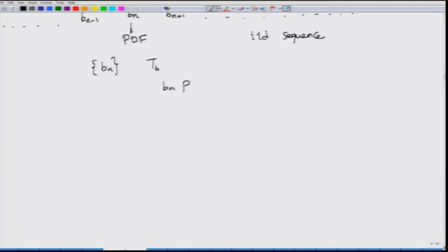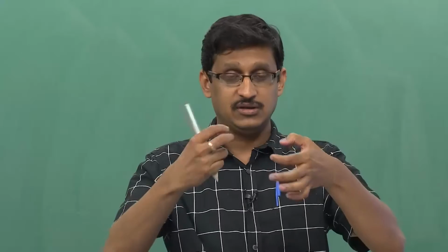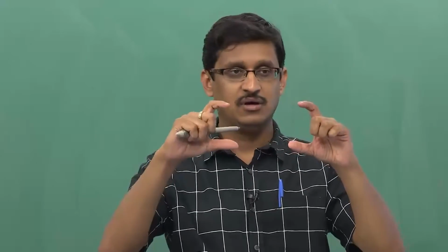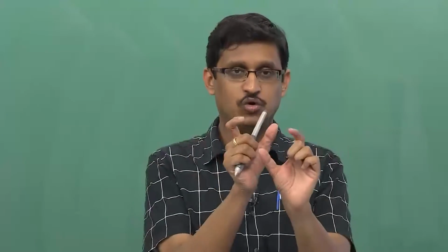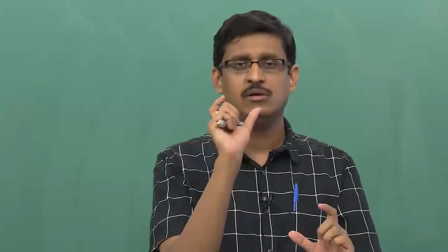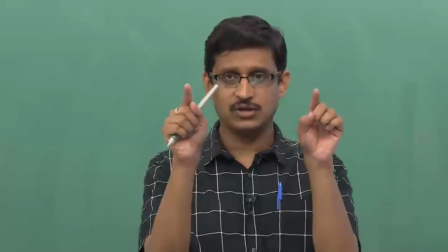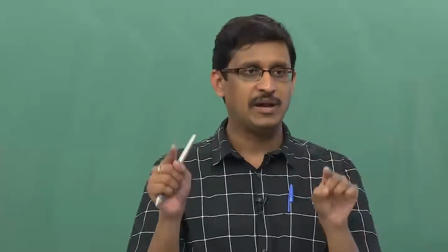If the pulse at time 0, some origin of reference that we are going to consider, will be lasting from 0 to TB, then the pulse in time duration 1, or time slot 1, will be from TB to 2TB. Then you have 2TB to 3TB, 3TB to 4TB, 4TB to 5TB, and so on. So, you just give an appropriate number. Think of this as a train having these bogies. Each bogie will be represented by a number: -1, 0, 1, 2 and so on. You can even think of the bogie shape as the pulse waveform.